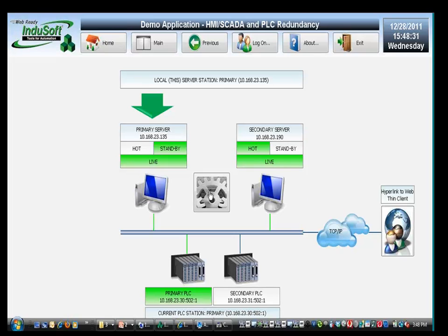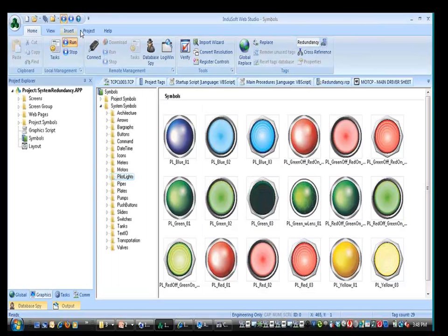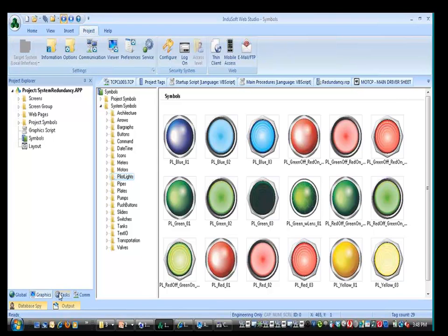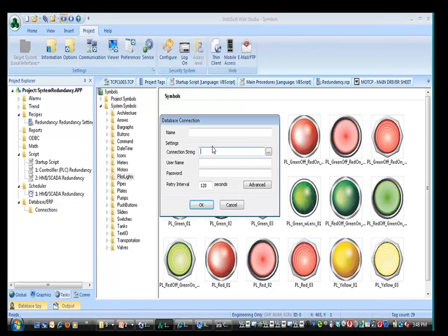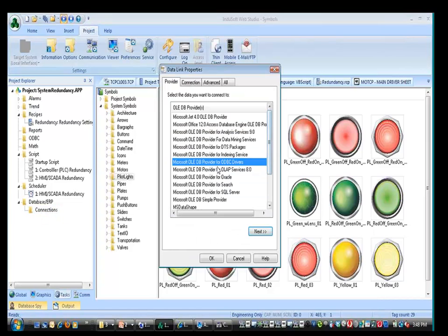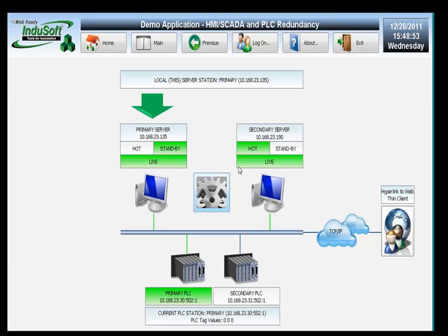And if you're asking about the redundant database configuration, the answer is yes as well. Because when you go to the database configuration, where you define the connection string, you can either hard code it, or you can write a string tag between curly braces in this field, and by changing the value of this tag, you change the connection string to the databases on the fly.